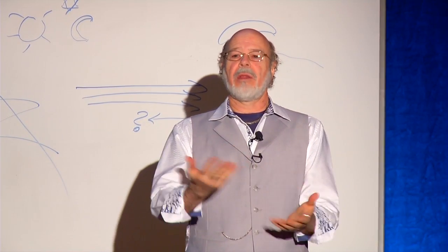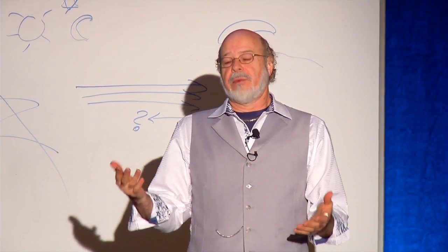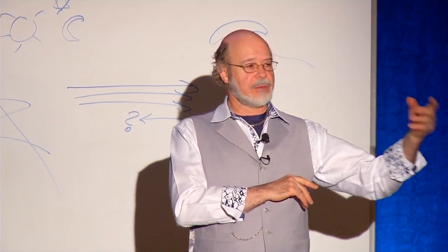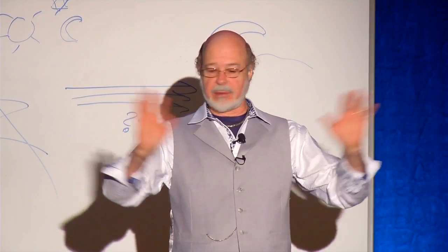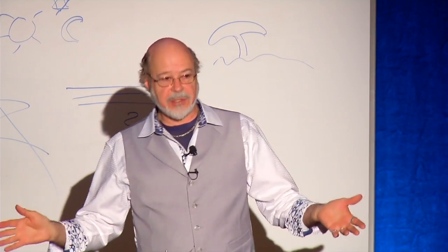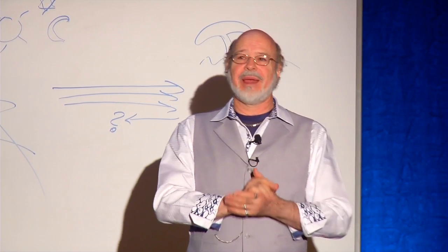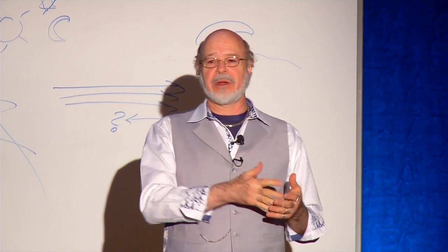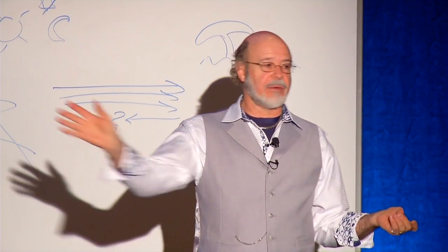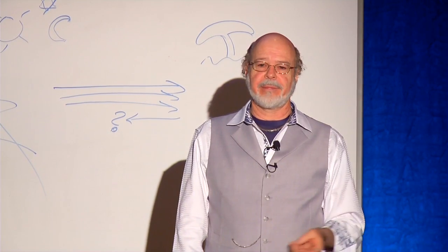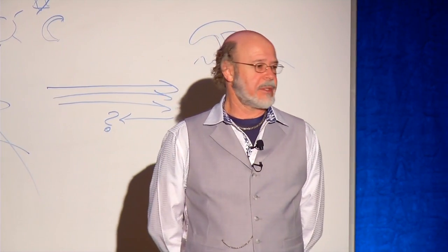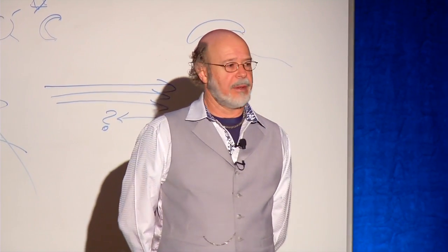But that's all the way from there to little things like, we changed our mind recently, but there was a problem, and somebody got sued from slipping on polished stone. For a while, it was like, we don't do anything but honed stone. Now we've changed that. But for a long time, probably until somewhere in the early 90s after I came with the firm, we as an office just would not do polished stone on the floor. And that was all before the ADA slip resistance requirements, which kind of made it moot.